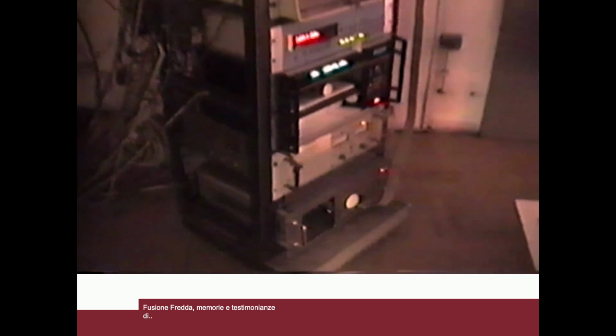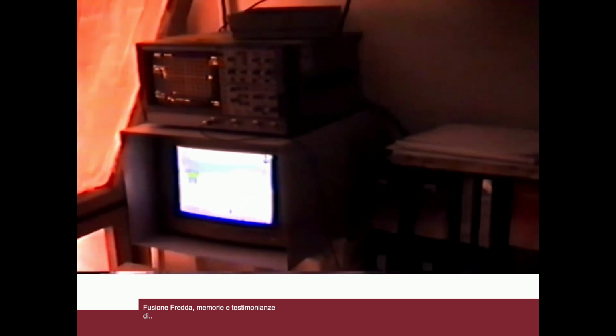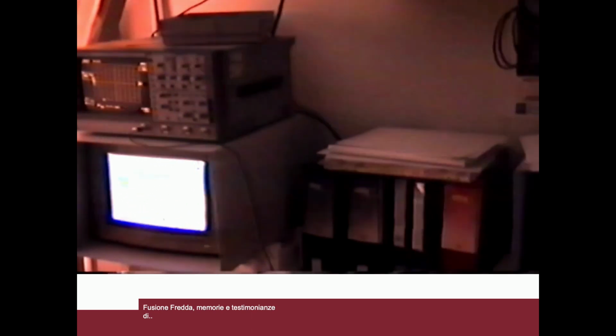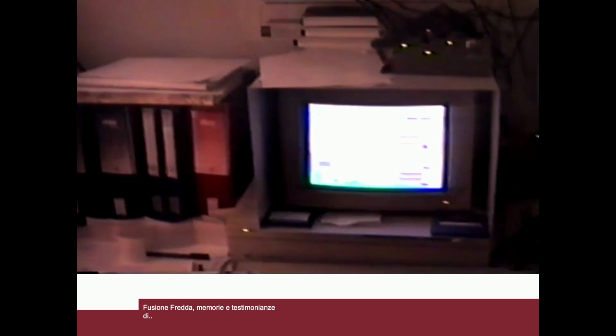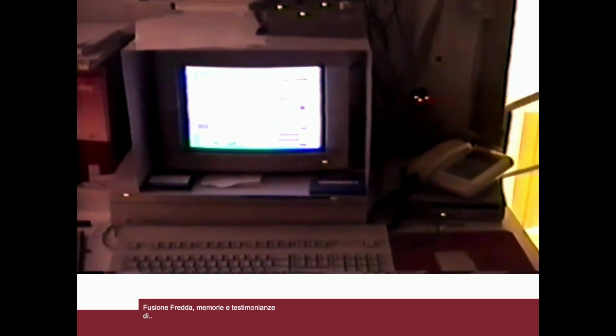Below there is a rotary strip recorder that records the temperature of the 4-cylinder heating system of the recombiner you have seen before. The first computer you see is a Macintosh FX running on a program made with LabVIEW. The assigned function is to acquire the shape of the pulse associated with each neutron detected by the neutron counter, through the connection with the digital oscilloscope that you see.